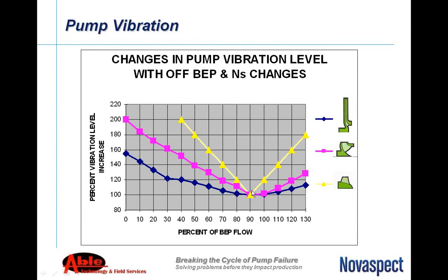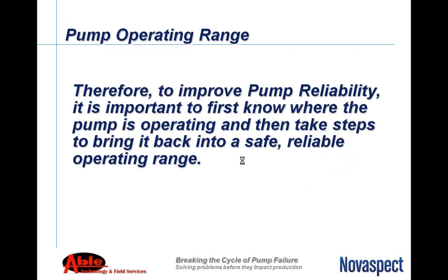So as this happens, I'm going back to this BEP again, and this is the key thing. If you pick up anything today, it's that best efficiency point. How close is my design point to my best efficiency point? As you can see, the loads with a little bit different impellers, but your vibrations do pick up as you pull away from BEP. And Craig's portion of it, he's going to talk a lot about this when you start pulling away from your BEP and how we're going to go about monitoring those vibrations.